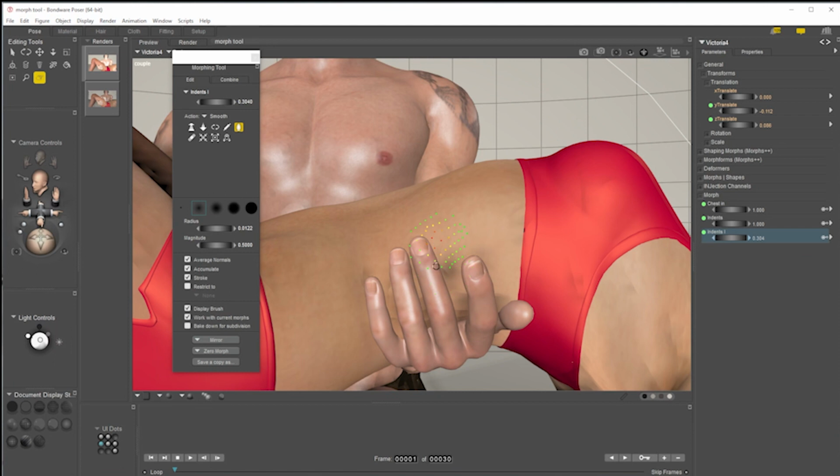So just gently add this. Okay, maybe a bit more magnitude. Okay, that's maximum. And for those of you who are used to 3D modeling, this is the equivalent of the relax command, where it brings the vertices more in line with each other. What it actually does is bring the vertices that we moved back more to their original position, which has the effect of just smoothing the whole thing out.